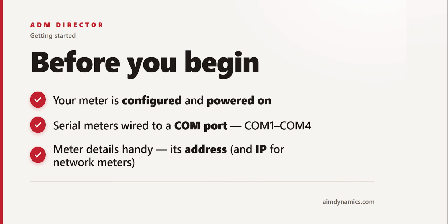First, make sure your meter is configured and powered on. Second, if it's a serial meter, it should be wired to one of the gateway's 4 COM ports, COM1 through COM4. And third, have the meter's details handy, its address, and for a network meter, its IP address.